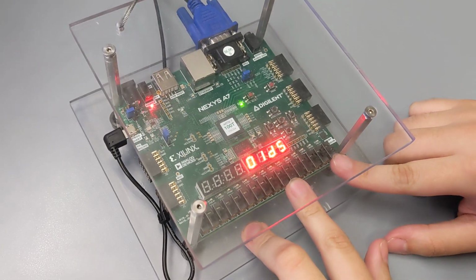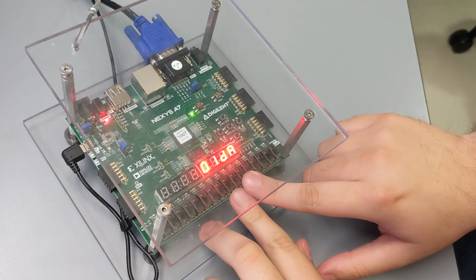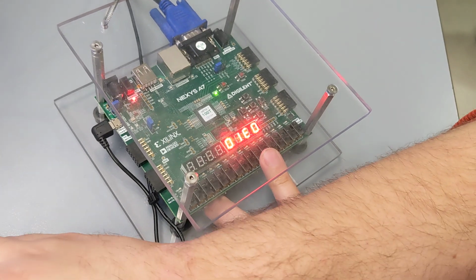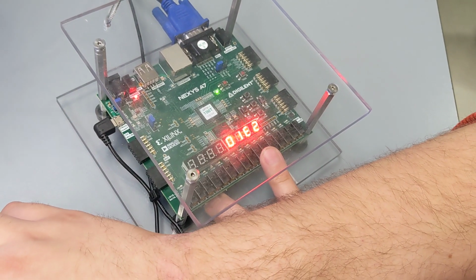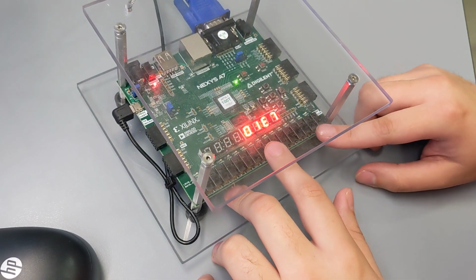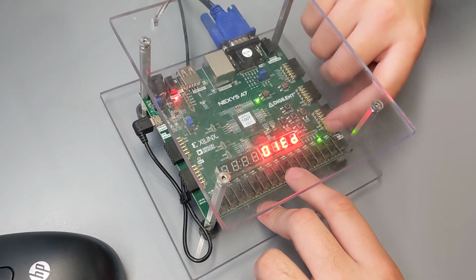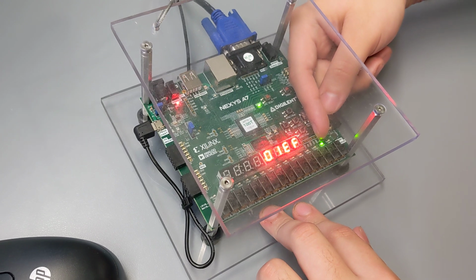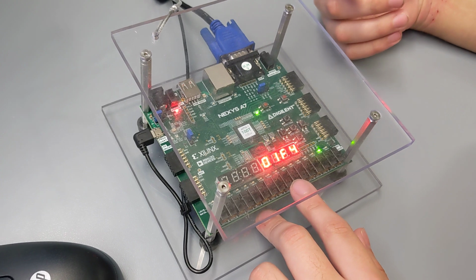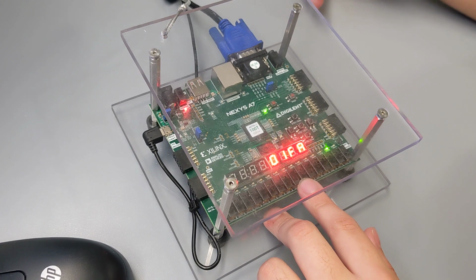So for the ALU, we added on the 5th bit. This is CN, and this would be mode. If you hit that, I believe we are on arithmetic left for 1 bit for A, if I'm not mistaken. Give me a second. Sorry, we're doing arithmetic right for A by 1 bit. So for example, if we hit 2, this first LED is C out, and then this next LED would be 0001, which makes sense because if you have 2, which is 0010, and you shift it to the right by 1 bit, you get 0001.